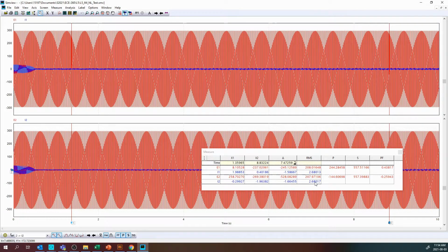Because there are small variations in the machine, so resistances are not exactly the same, and there are other non-linear factors that are going to be present. How the squirrel cage is made, or if it has imperfections, can change a little bit what the current is going to be on each of the three phases. But because this is a simulation, you don't have that issue, okay?